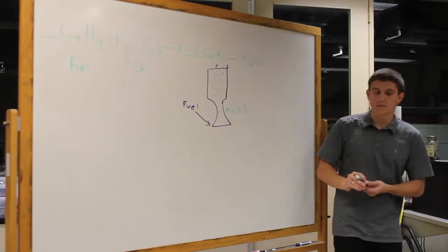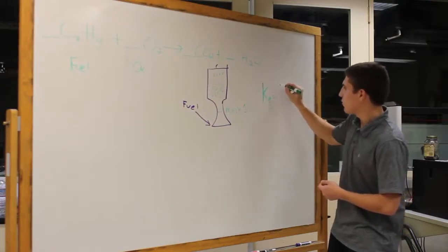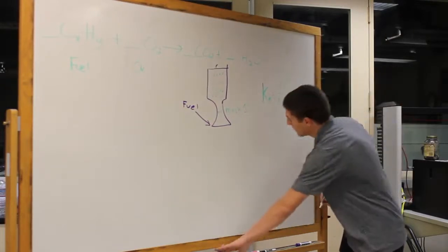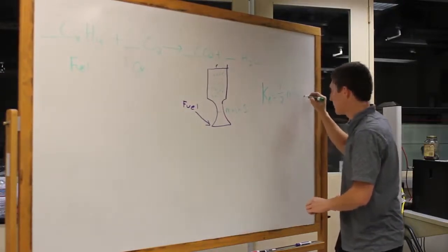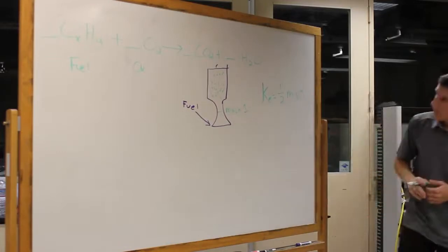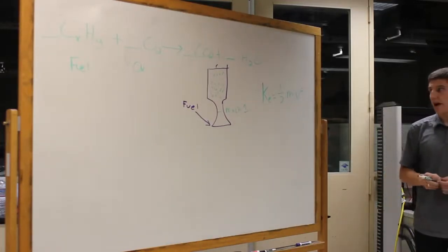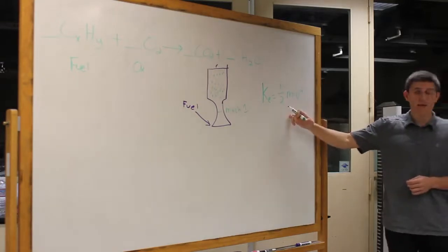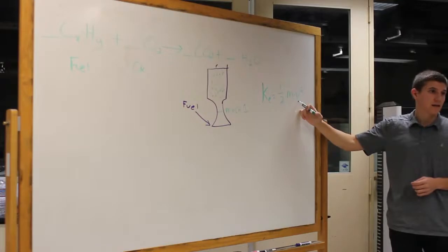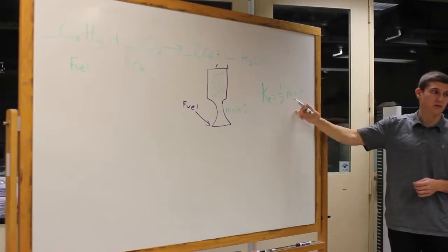And this all comes down to your basic physics, where K, the kinetic energy, is equal to 1/2 m v squared. So the most efficient rocket reaction you could ever have with combustion uses the lightest mass, because that'll give you the greatest velocity. Velocity is a squared term, whereas mass is only a single term, first order.